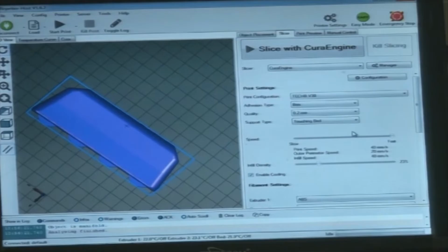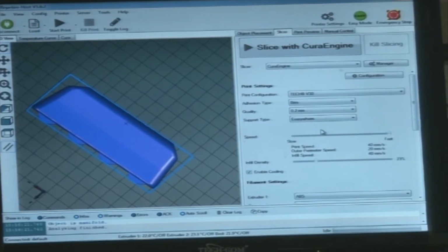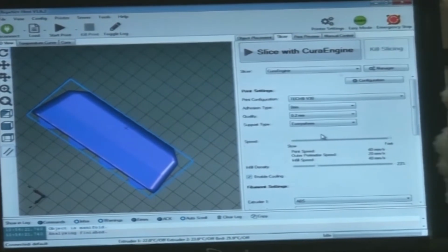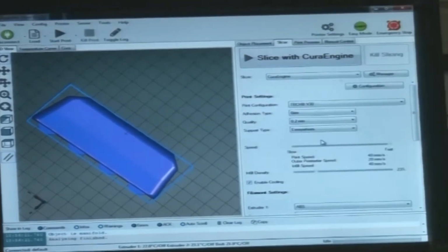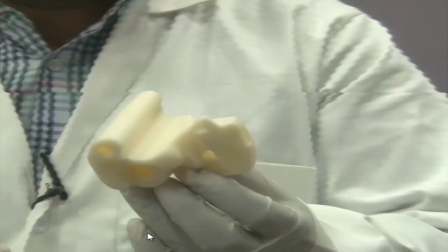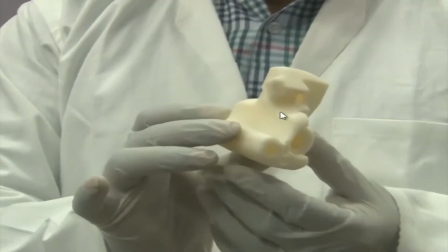If we are not aware, or we do not have any information about what the CAD model would be from inside, or there are different intricate features, in case of highly complicated CAD models, where there is no flat shape anywhere, then we need to set this option to everywhere. So we are talking about the support type, and support type is set to everywhere. This is one of the jobs that is kind of complicated. So you can see there are multiple shapes here, okay.